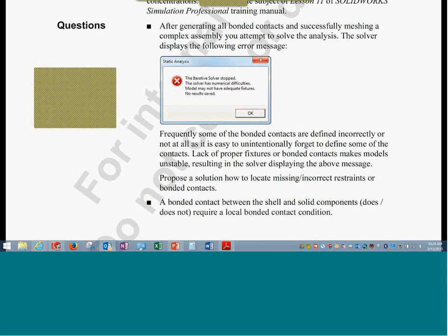Okay, so these three, and one option which I personally use sometimes is to switch off all the loads, have the constraints applied appropriately, and then apply gravity. That should help you find out which part is falling down or where a typical solver might fail. If it is iterative, you can stop it and see it, or you can use soft springs, and that can help you visualize it.